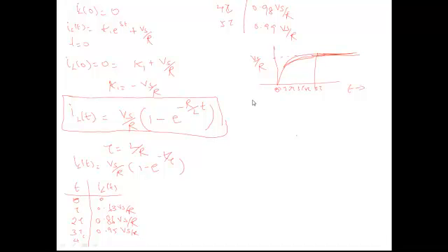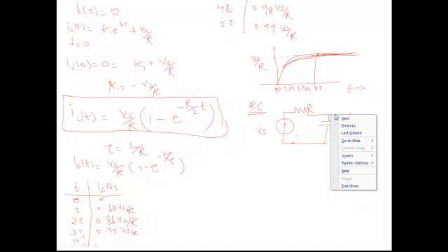Now next let us see the same combinations for the RC network. Say, for example, you are having a source with R and C. As I told you earlier, capacitance will store energy in an electric field. Therefore, we are interested in finding the voltage across the capacitance. Always solve first for the current through the inductance and the voltage across the capacitance. Since this circuit involves capacitance, you apply Kirchhoff's current law at this node, call it node A.